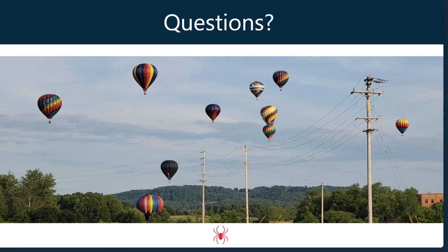Great, thank you. Next question here is, what types of load scenarios are available in SpidaCalc, and can I create my own? Yep, so SpidaCalc uses a client file, which is what we've called where we store all of the specific information related to your unique instance of SpidaCalc. So that's going to store not only your specific properties for your wood poles or concrete poles and your wires, it will also store your load cases.